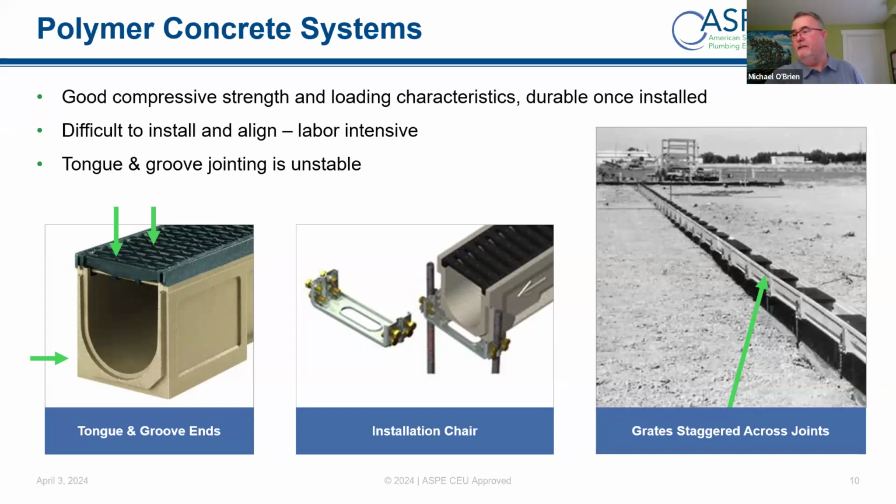Shifting is quite common with these in the process of pouring the concrete. Obviously the concrete is trying to displace area and trying to move some things out of the way, and as you're leveling it and trying to make it slope properly, you're kind of fighting that concrete to keep your work straight.